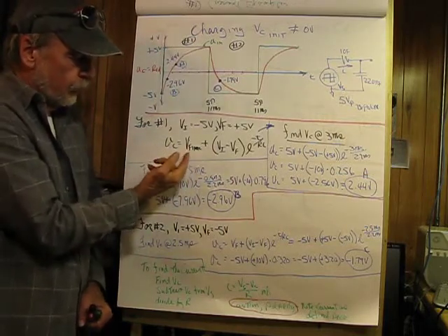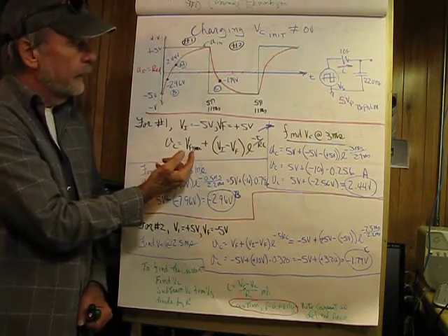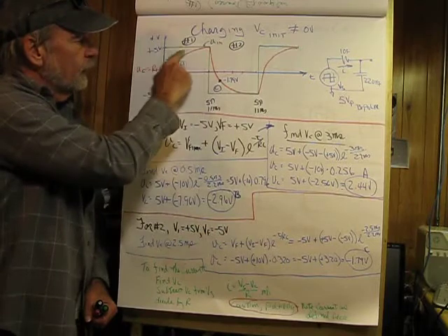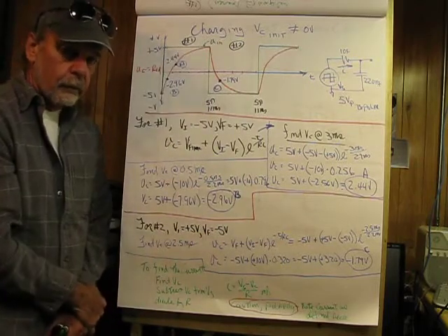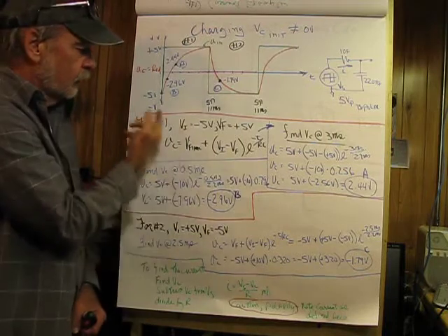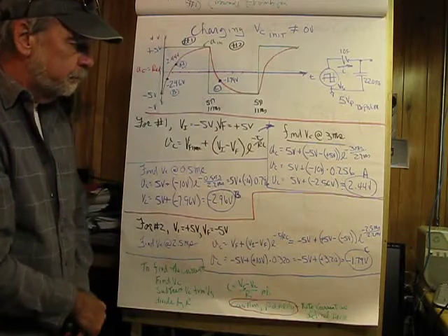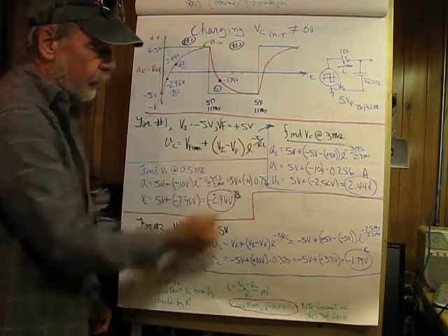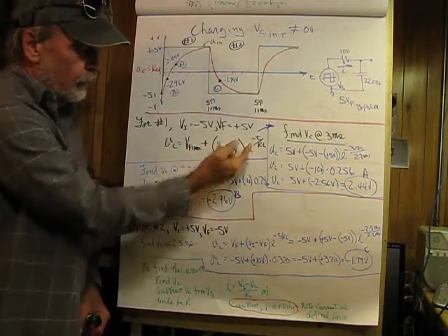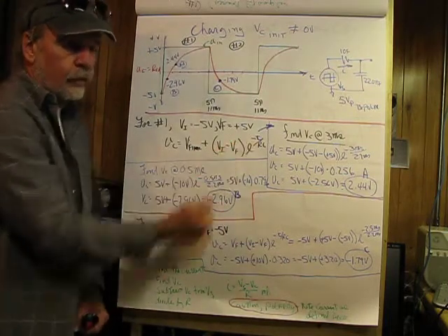The capacitor voltage is going to be equal to V final, and I'll be using VF from now on. For number 1, V final is going to be +5 volts. That's where we're going to. And V initial is -5 volts, which is where we're coming from. And then we have the standard e raised to the -t over RC, or if we like, -t over tau.